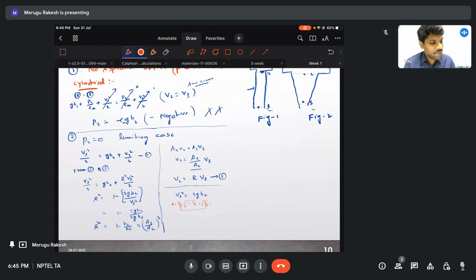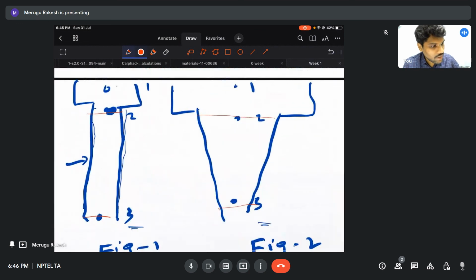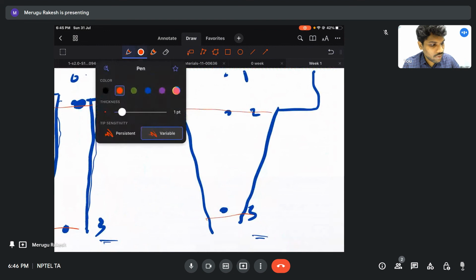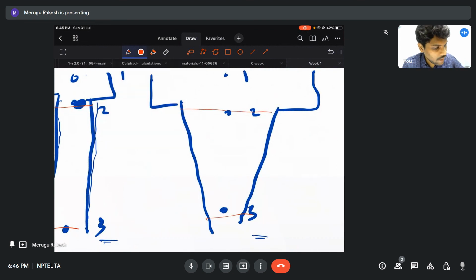I want to explain this because there were so many doubts on why we have to take a sprue, and why not the shape of the sprue as this taper shape, or why not cylindrical. Actually the shape is not exactly the taper either, but for study purposes we follow the taper, while the actual flow will follow this kind of design.